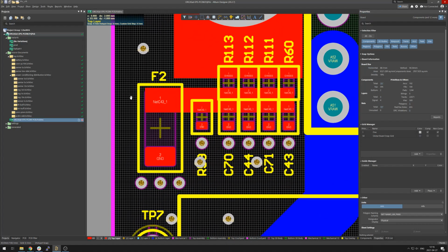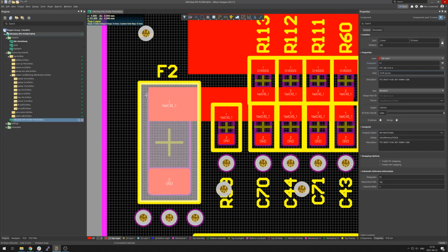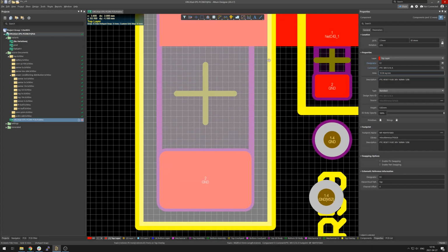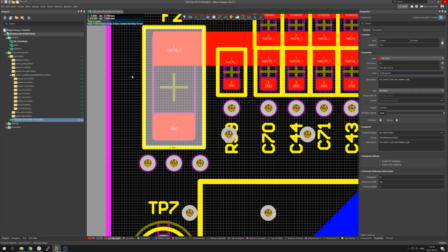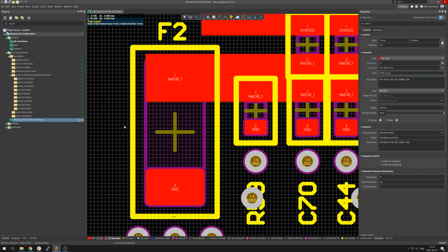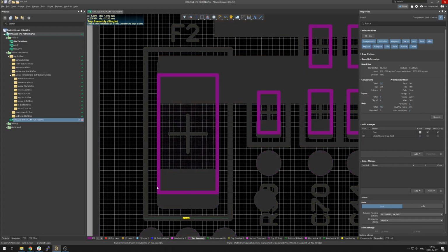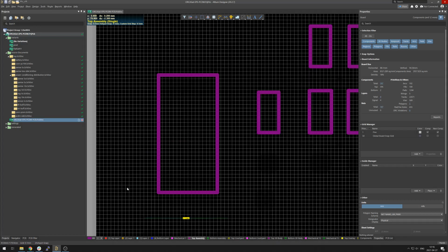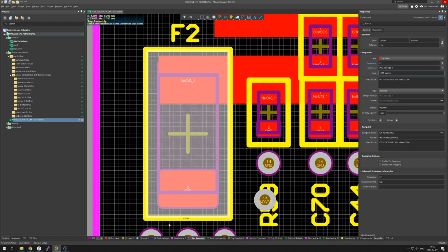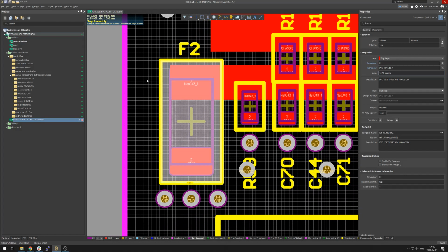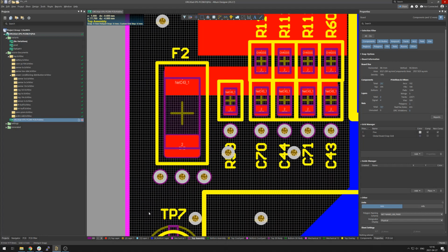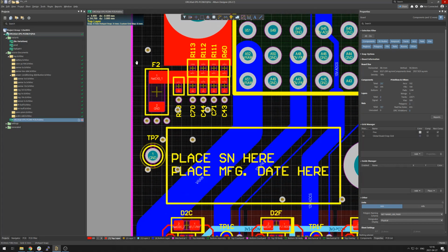But anyway, if you do have heights, then Altium either generates this number through the IPC compliant footprint wizard or calculates it automatically. How it calculates it is it basically looks at the footprint, and this gray box, when you select the footprint, it just grabs the X and Y of that gray box. So it's not exactly accurate because, as you can see on the top assembly layer, the component is actually this big, but Altium is saying that the component is this big because it's the whole footprint. It's not totally accurate, but it's good enough, and it'll save you a bunch of time when generating the BOM. So how do you get this data?